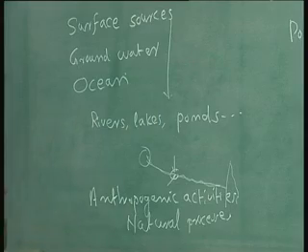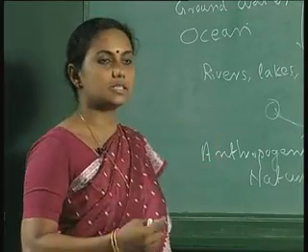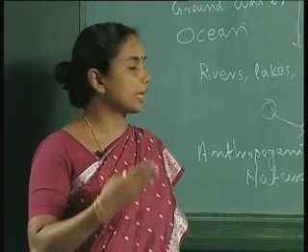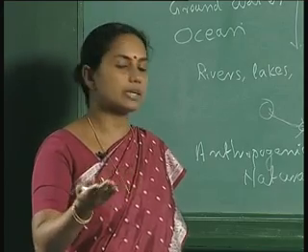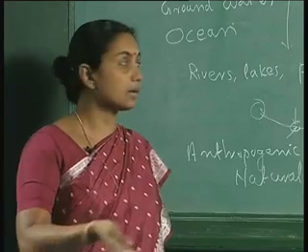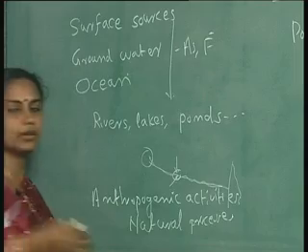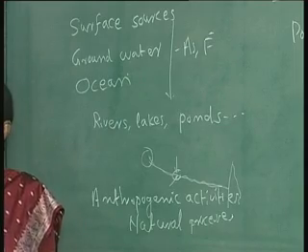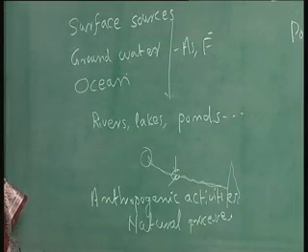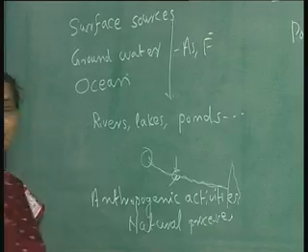But when we talk about groundwater, the pollutants may be due to natural causes, because of the geochemical or soil properties of the aquifer. The water is always in contact with the soil and minerals. If the minerals contain pollutants like arsenic, fluoride, etc., they get dissolved in the water and definitely the water will be polluted. So in groundwater the pollutants can be mainly from natural sources, but in surface waters it is because of anthropogenic activities.